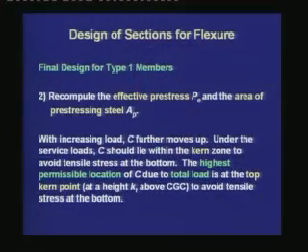Now, once we have known Pi, we can calculate P0 depending on whether the section is pre-tensioned or post-tensioned. Once we know P0, we are able to estimate E. Our next step is to recompute the effective prestress PE and the area of prestressing steel AP.